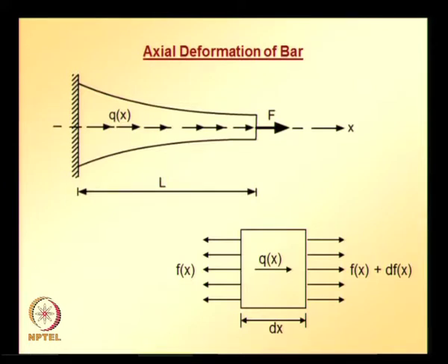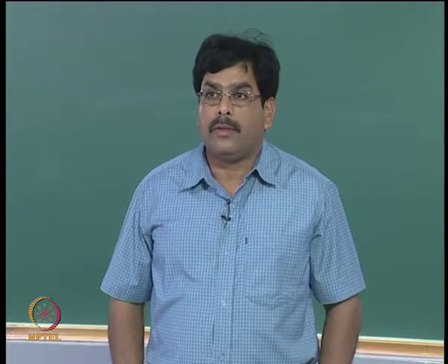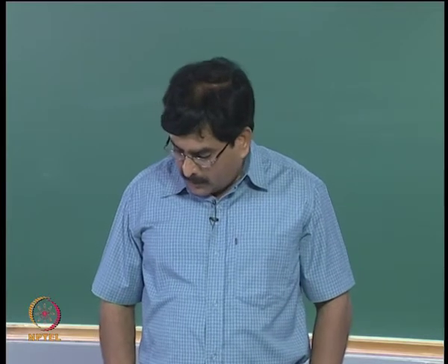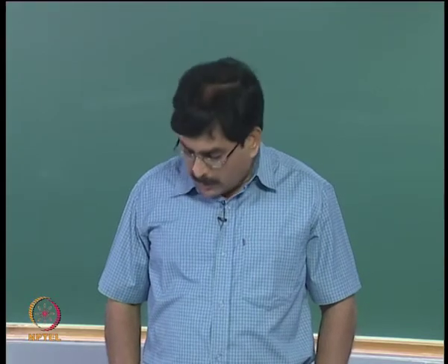So, the governing differential equation explaining the physical phenomena here, that is axial deformation of bar, can be derived by considering equilibrium of forces acting on an infinitesimal bar segment as shown in the second figure. And please note that the sign convention that we are following is tension is positive. So, if you look at the equilibrium of the infinitesimal element that is shown,